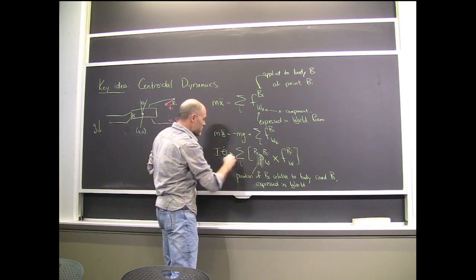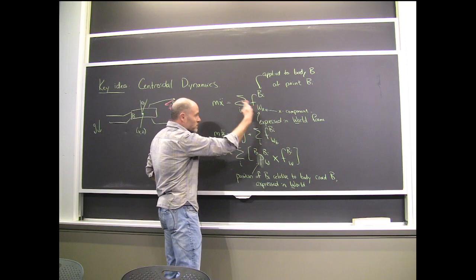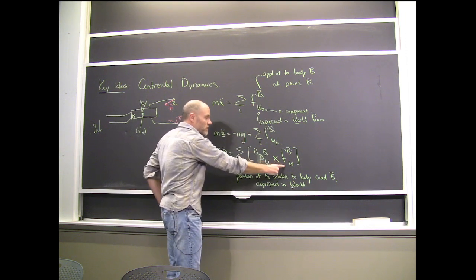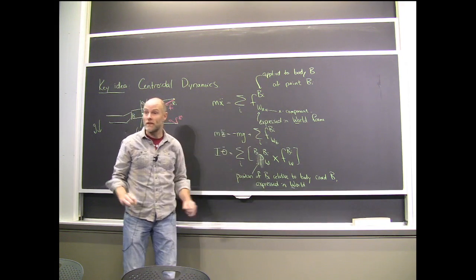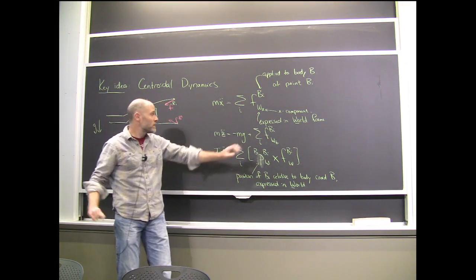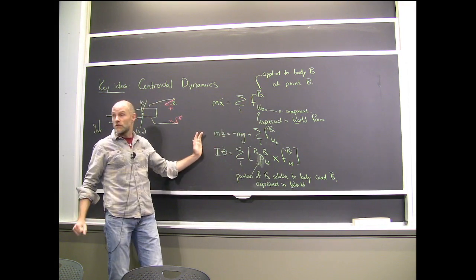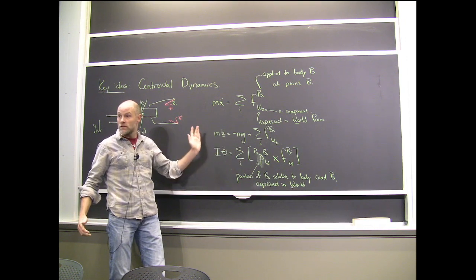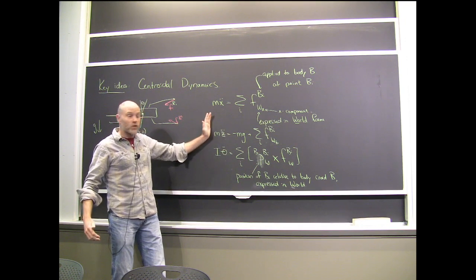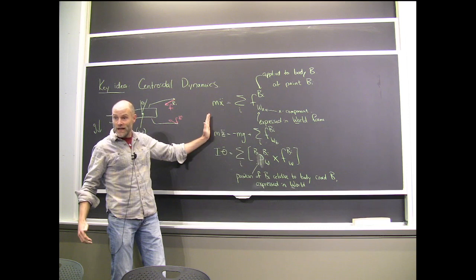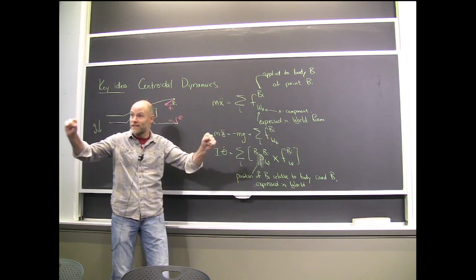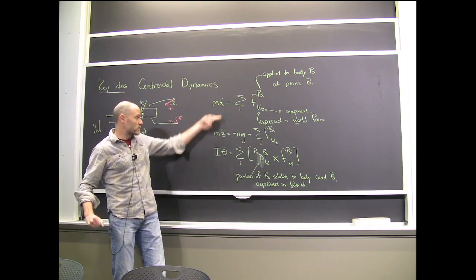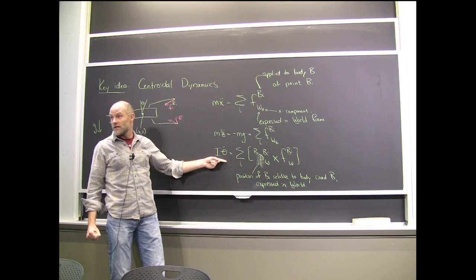Okay, then actually the dynamics are linear, or affine in this case. They're actually affine in the forces. So if I think of forces as a control input, then I actually have a linear system of equations, or affine systems of equations. I could do LQR on this. I could do linear model predictive control on this if I took the forces as my control input, and I just wanted to control the motion of the center of mass.